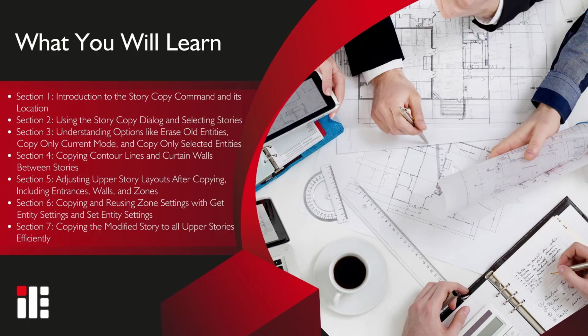In this video, you'll learn how to use the story copy command in ideCAD to create upper stories quickly and accurately. We'll cover selecting stories, copying contour lines and curtain walls, and using options like erase old entities or copy only current mode. You'll also see how to adjust layouts, remove entrances, redefine zones, and copy zone settings between zones. Finally, we'll copy the modified story to all upper levels, completing the building efficiently. By the end, you'll know how to manage story copying with precision in ideCAD.